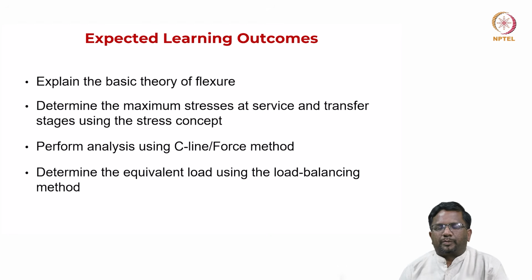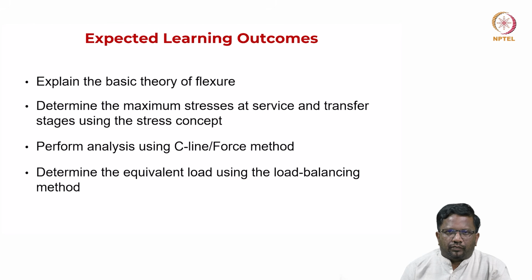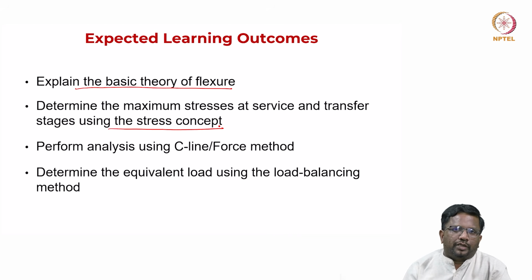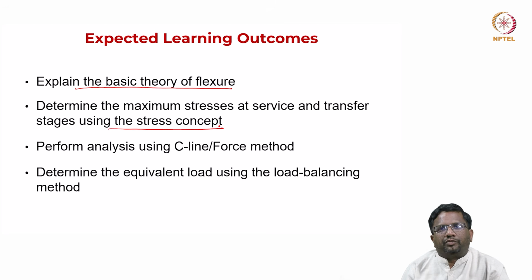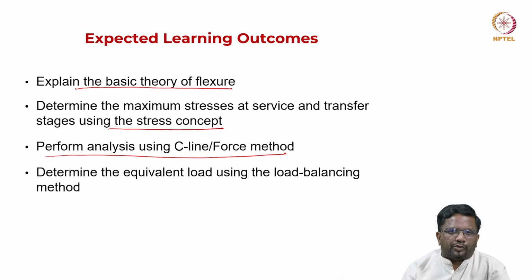Right, so what are the expected learning outcomes of this module? The student should be able to explain the basic theory of flexure, and then determine the maximum stresses under service conditions and transfer conditions using the stress concept. There are three concepts of analyzing a prestressed concrete section and member. Then we will also move into the C-line or force method of analysis.